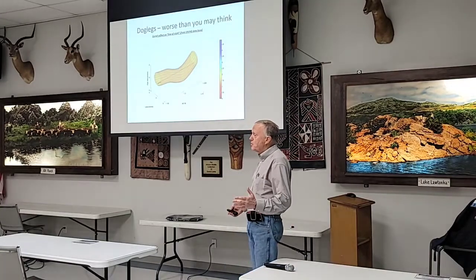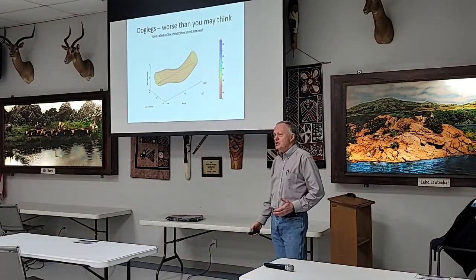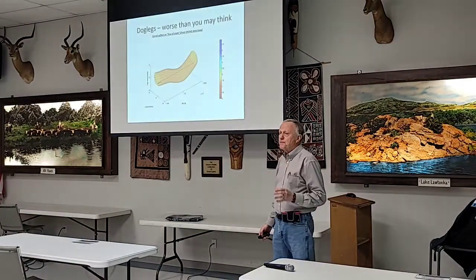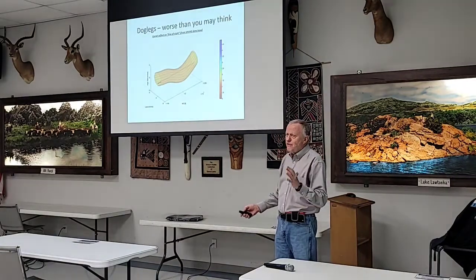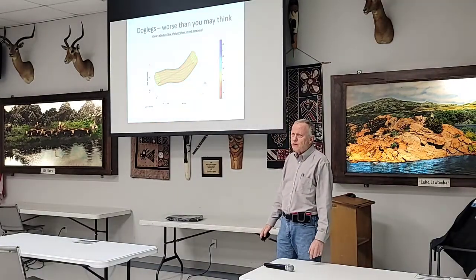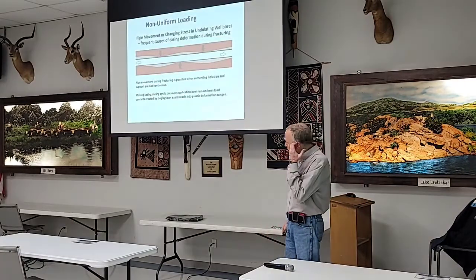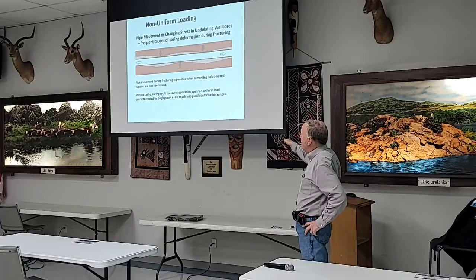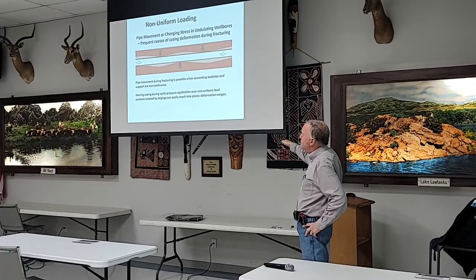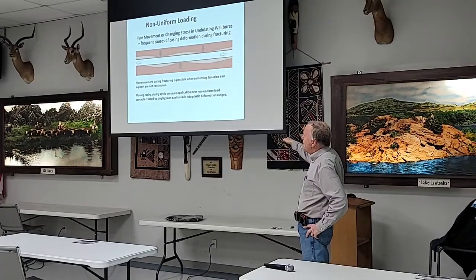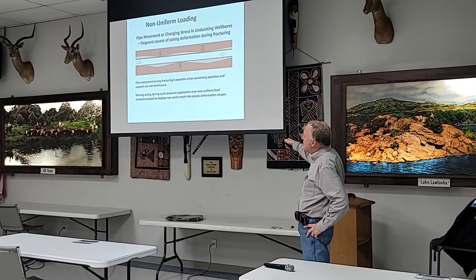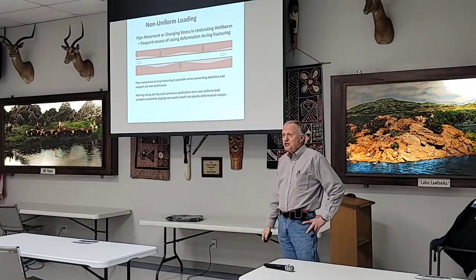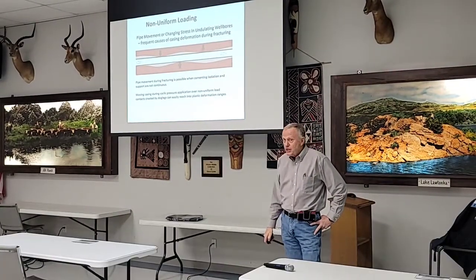So if you have some drilling problems in there, if you think that you're seeing a possibility of that, please get a fingered caliper. There's other things you can run, but we've had more luck with a multi-fingered caliper than anything else. What we're seeing is if you've got undulations going through here, dog legs, and you run that pipe, let's say you can get the pipe in there. As you frack, the pressure will be at non-uniform loading points. That is the lead off here on the mechanical side.